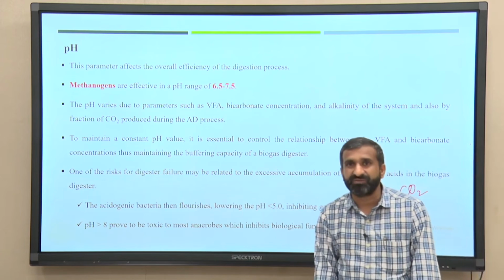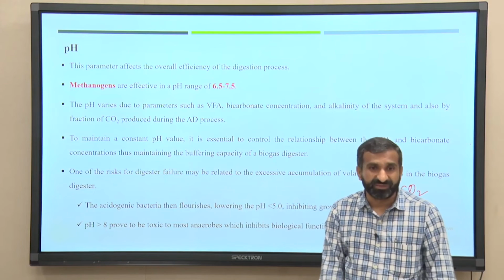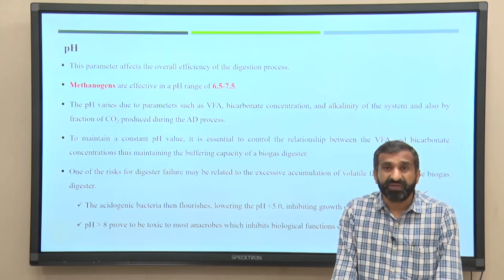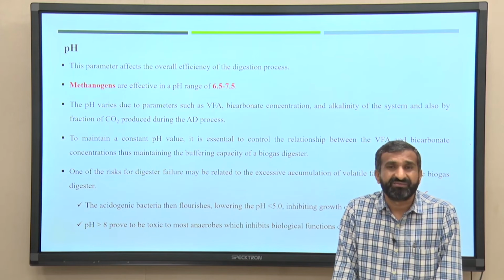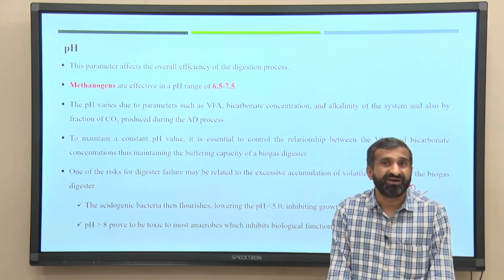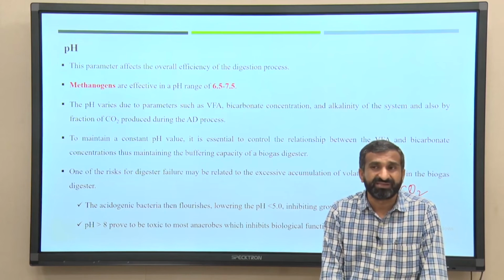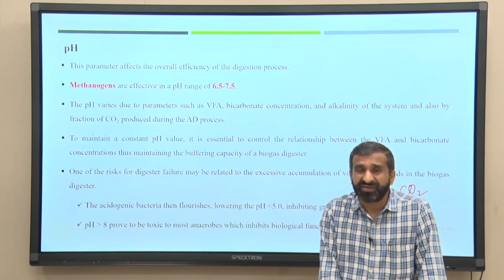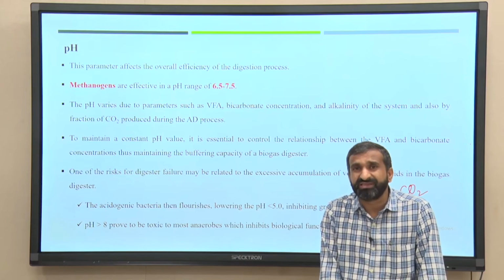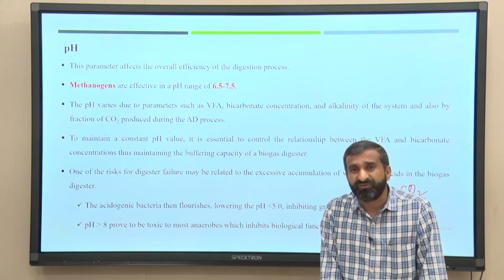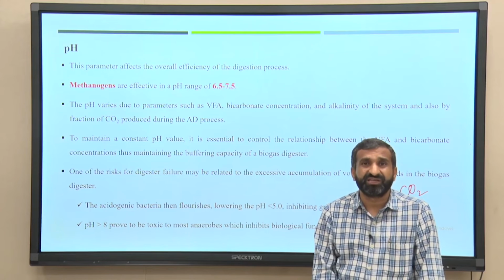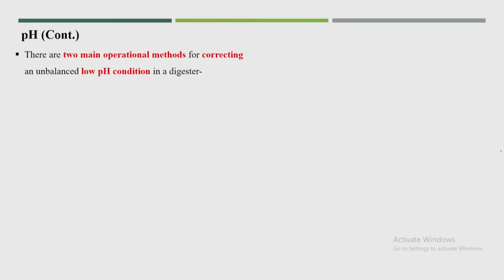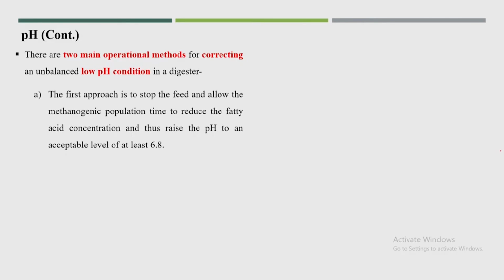So, what is important here is to maintain the pH, and this is possible by addition of a mix of different organic residues. Suppose you are planning kitchen waste, it is good to mix it with another kind of material which will maintain a particular pH. Or your reactor has to be acclimatized to neutral pH, and slowly this acidic kitchen waste could be fed into the reactor, not at a very high rate, while checking the reactor pH.